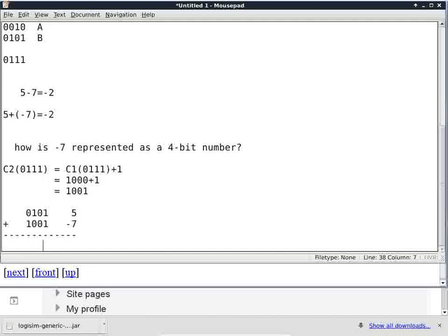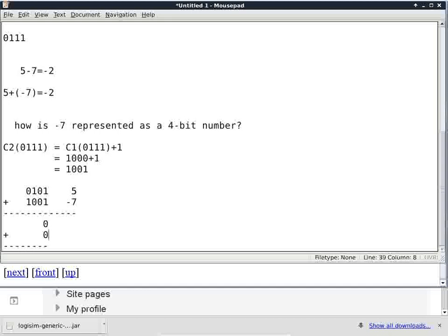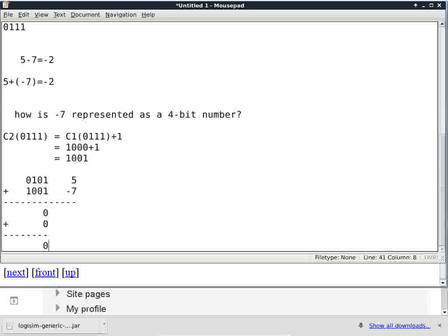I'll do the same thing as usual. This has a result of 0, and the carry from before is always a 0 because this is the least significant bit already. 0 plus 0 is, I have to put a 0 here, okay, because this 0 is due to this 0 plus this 0. There is 1 carry from this 1 adding to this 1. Okay? This 0 plus this 0 is a 0. This 0 plus this 1 is a 1. And neither gave me a carry, so this carry is going to be a 0 because it's an OR of the carry of both of those additions.